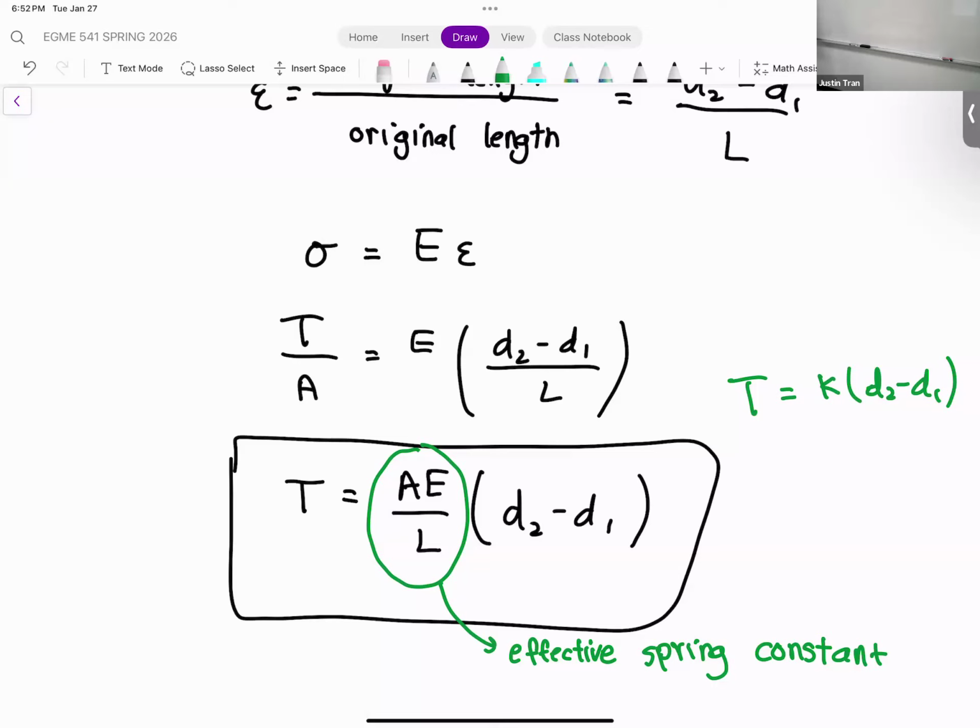And D2, D1, you said it's going towards the right. In the equation you put D2 minus D1. If the tensile force pushes the rod in the left direction, is that a negative D1? Exactly, that's why we have the minus there. We define the positive direction to go to the right, but we know it's going to go to the left. That's why we have that as minus. So it's already accounted for in the equation. Well, thank you, Dr. No problem.